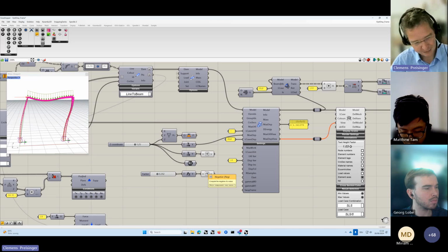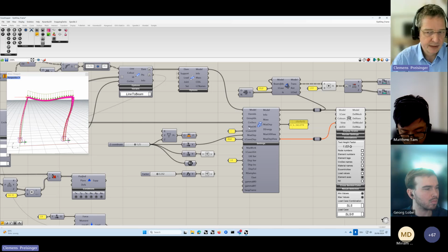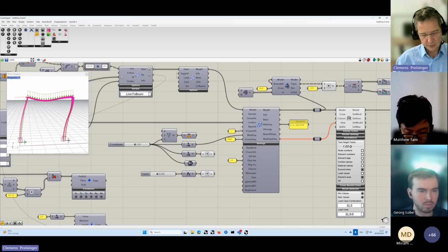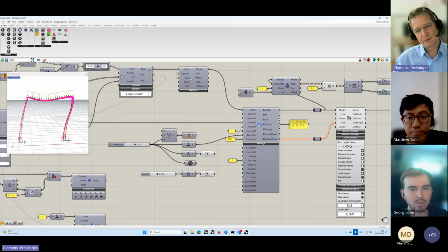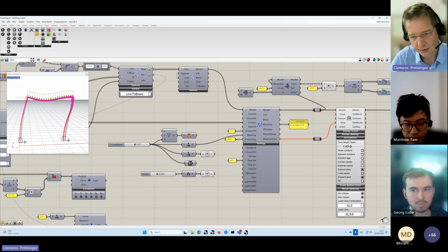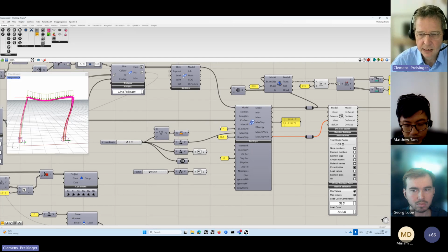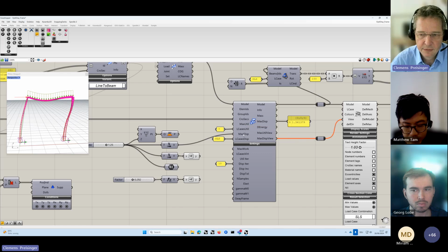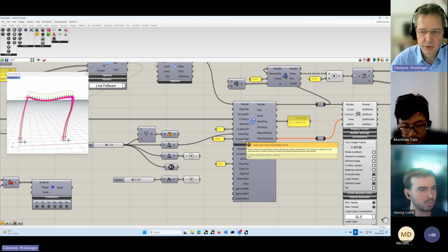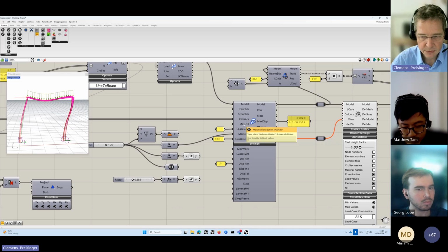I mean, the former method of working only with characteristic loads and then limiting the utilization to 70% can still be done. So this was also one of our aims, to not change the workflow of the past, but instead to take it and to add new features to it. And in case of the cross-section optimizer, there's now the option to have different load cases for the utilization and for the displacement optimization. You can set also different values, of course, for the two scenarios.